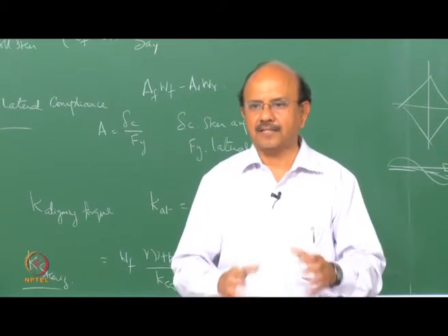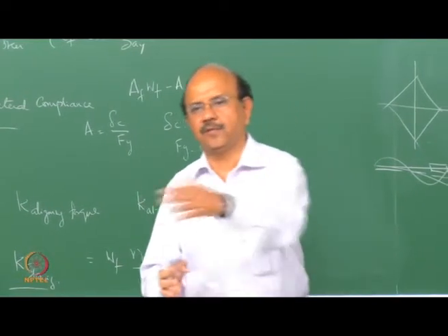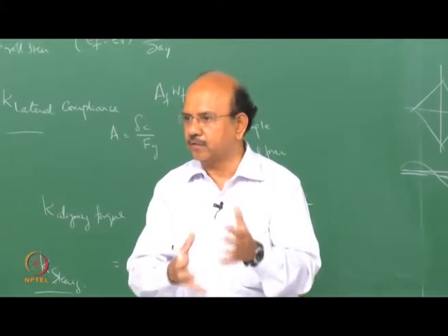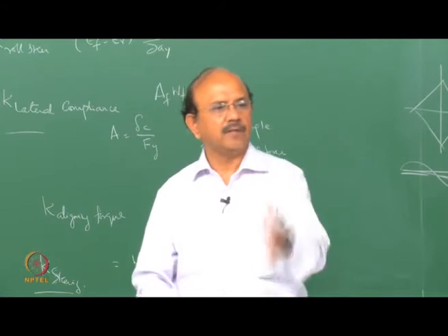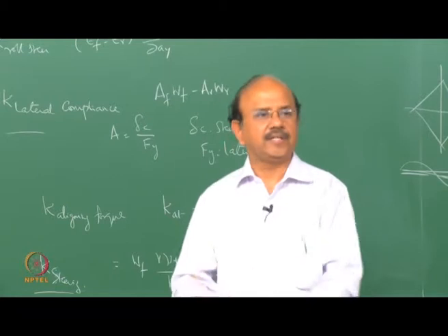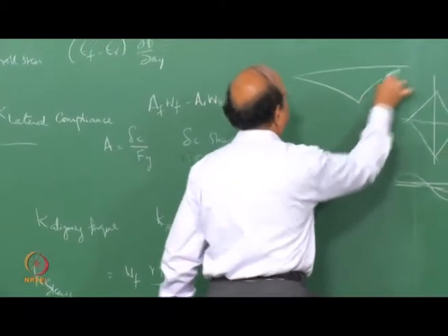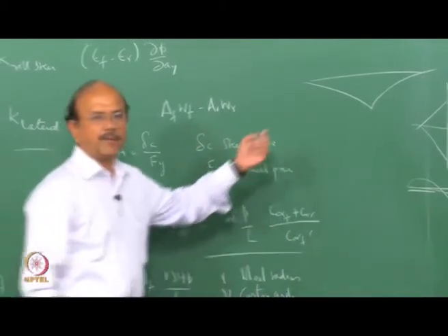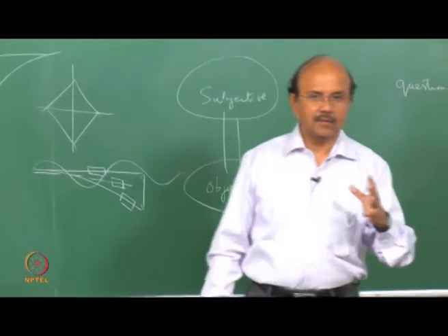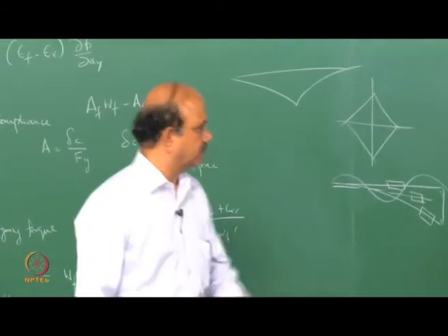Then I will take the car and accelerate. Loosely hold the steering, and see whether it is going to one side because of torque steer. It is steering on its own because of the acceleration that I am giving and because of the torque that is available at the wheel. When I decelerate, is it coming back? In other words, is the car having a path like that? First part is acceleration, second part is deceleration. So this is what is called torque steer. That's the next thing I will check, or you will check.